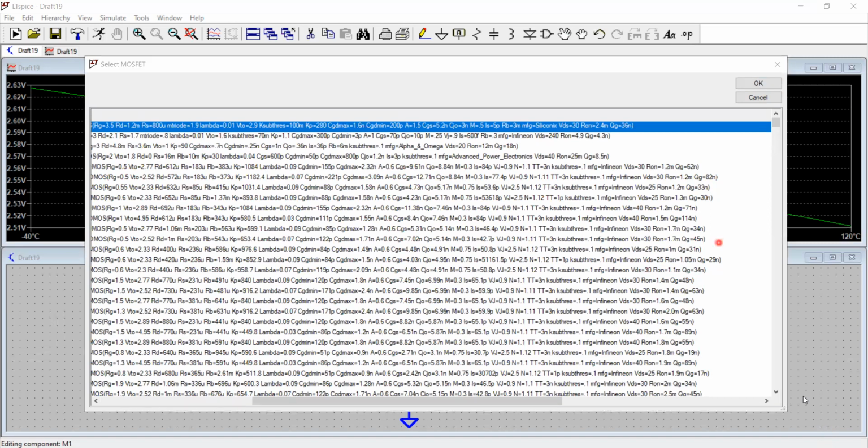Okay, and then you have LS RB, manufacturer name Siliconix. VDS is 30 volt, Ron is 2.4 milliohm, and the charge on the gate, 36 nanocoulomb. So it's a complete SPICE model.